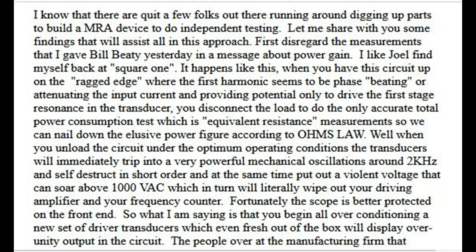Well, when you unload the circuit under the optimum operating conditions, the transducers will immediately trip into a very powerful mechanical oscillation around 2 kHz and self-destruct in short order, and at the same time put out a violent voltage that can soar above 1000 VAC, which in turn will literally wipe out your driving amplifier and your frequency counter. Fortunately, the scope is better protected on the front end.